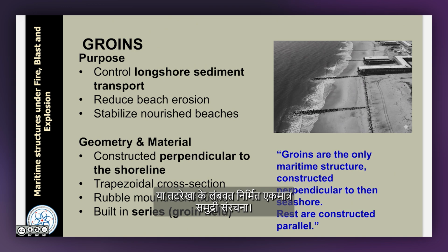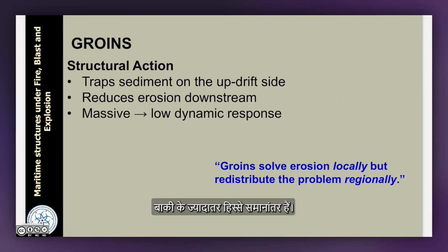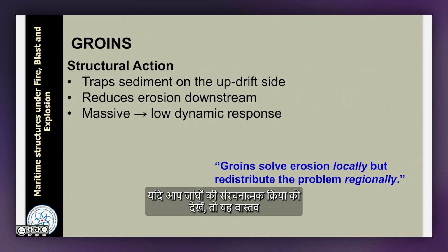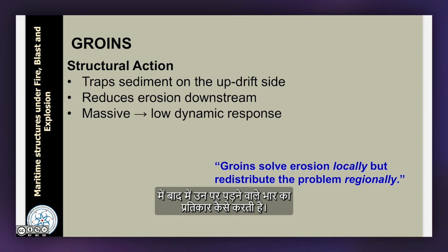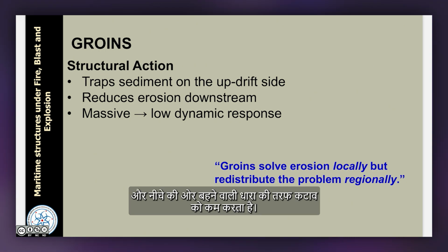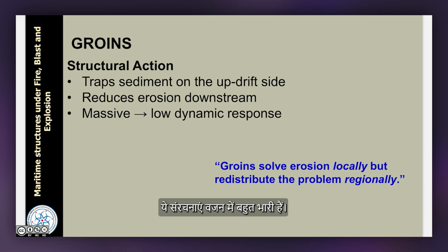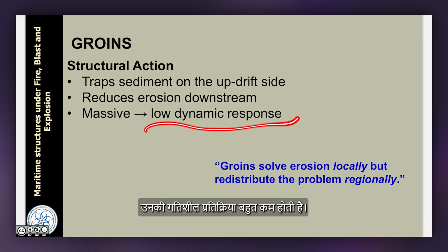Groins are possibly the only maritime structure constructed perpendicular to the coastline, the rest of them are mostly parallel. If you look at the structural action of groins, how they actually counteract the lateral loads acting against them, it traps the sediment on the updrift side and reduces the erosion on the downstream side. These structures are very massive in weight, they have a very low dynamic response.